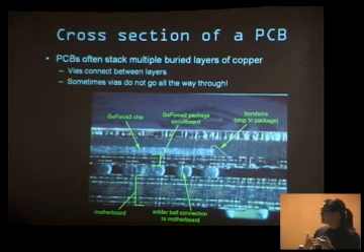If you look at the cross-section of a PCB, an important thing to remember is that there are multiple layers. This is actually a GeForce 2 graphics card that I took to a belt sander and sanded back. So this is a cross-section. Here is the BGA package itself, and these are the balls underneath. This here is the silicon chip, and you see the bond wire going down to the package, and there's a via right there. And this here is the heat spreader with the heat sink. This mates to the circuit board it's mounted on. You can see there are these pieces of buried copper on the inside. You've got to remember that they can hide traces on the inside, so you have to look out for those when you try and trace out a motherboard.